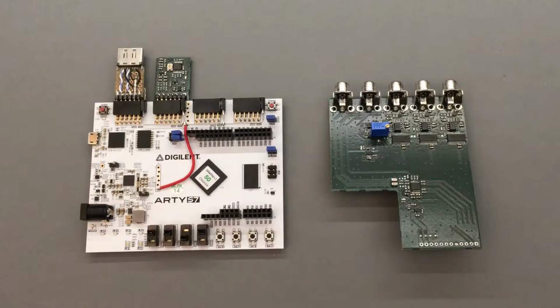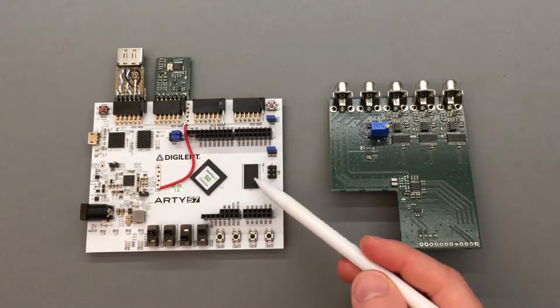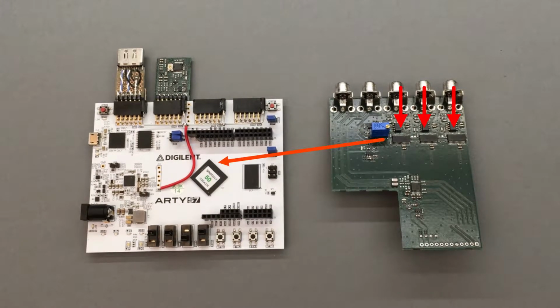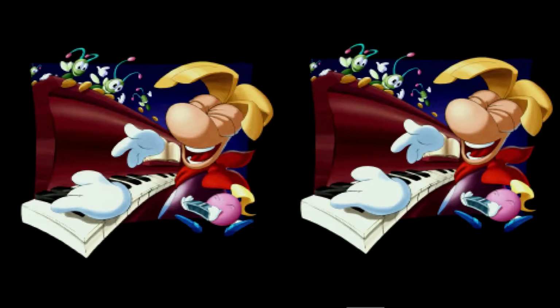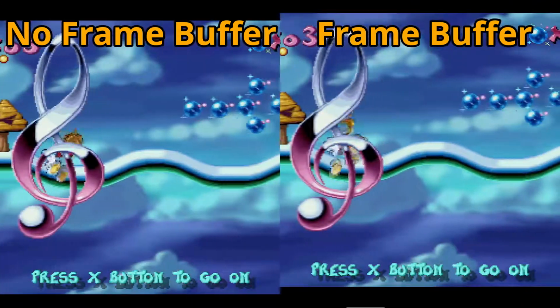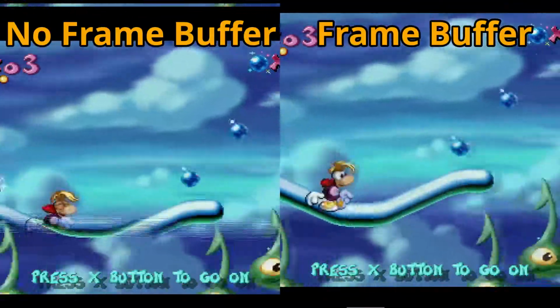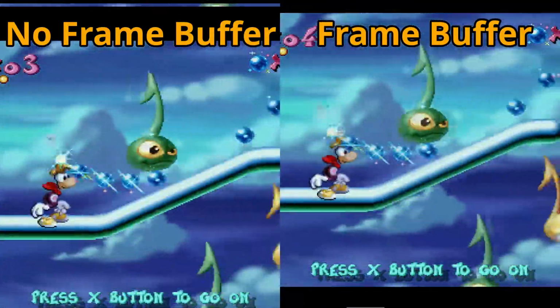The main upgrade this time around was the implementation of a full frame buffer using this 2GB RAM module present on the FPGA evaluation board. All incoming video information is stored in RAM before being displayed on the digital output. Using a frame buffer helps a lot during temporary loss of synchronization between input and output frame rate, as it always stores enough information to display a full frame.